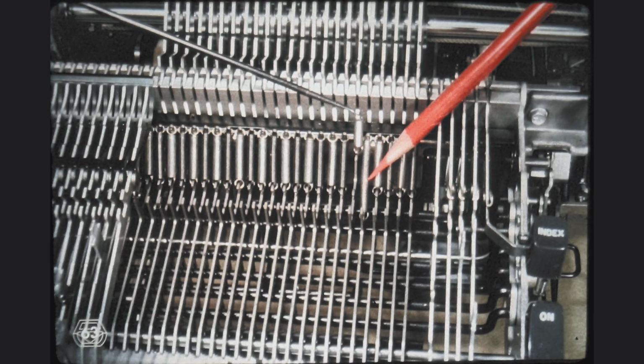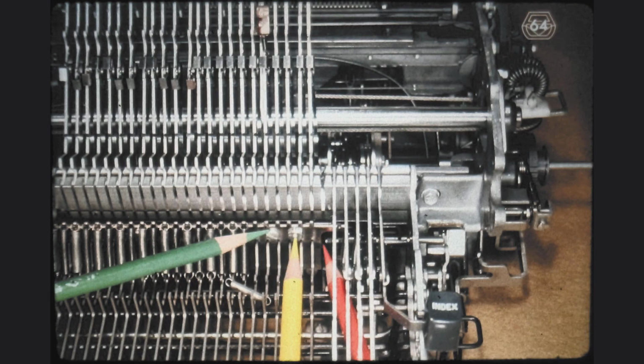Let us now remove some of the interposer restoring springs, starting with the spring to the left of the indicated underscore interposer restoring spring, and then removing all 4 of the interposer restoring springs located to the right of it. Removal of the springs enables us to examine the screws which support the compensator tube. The red pencil points at a slot through which one of the steel balls of the compensator tube is barely visible. The blue pencil indicates one of a total of 4 screws which hold the compensator tube assembly in position, together with the rear interposer guide cone.